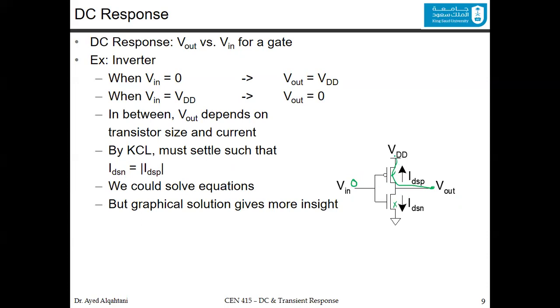And it is charged by having a current going in this direction. We call it the IDS. IDS is the one that you know from the transistor theory, but now we add P for it to indicate that it's a PMOS. Now, the output also is logic 1 since it's an inverter, and the connection is very clear. The VDD is coming out in the V out.